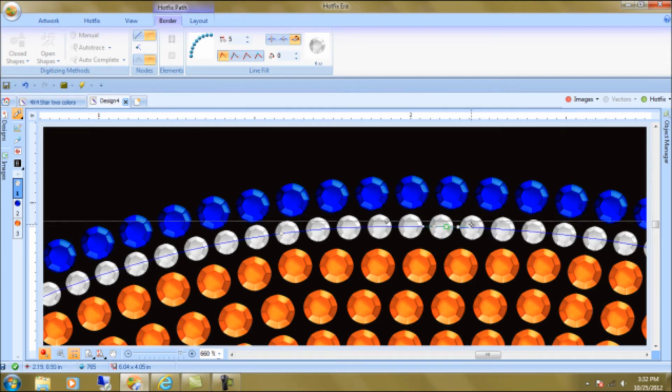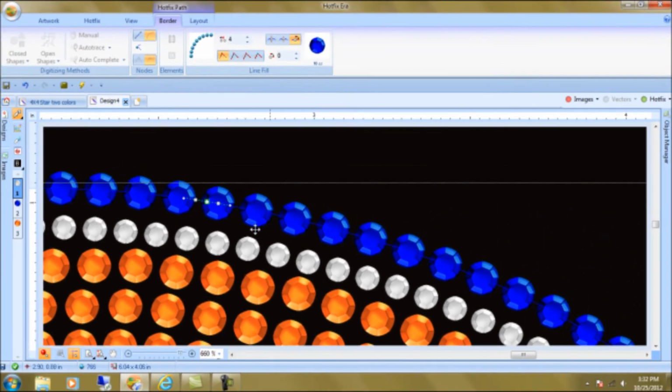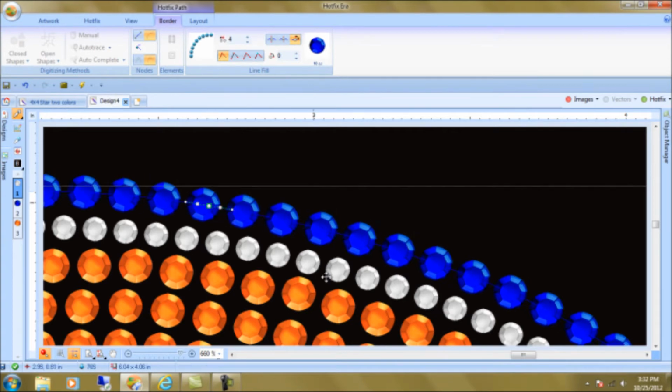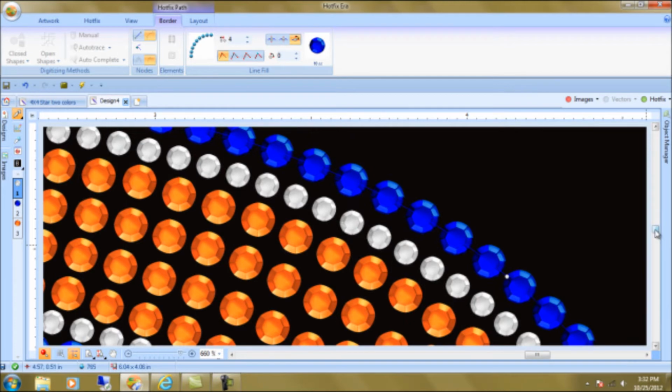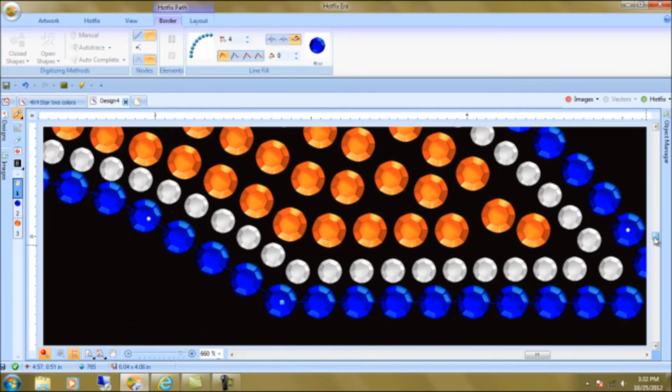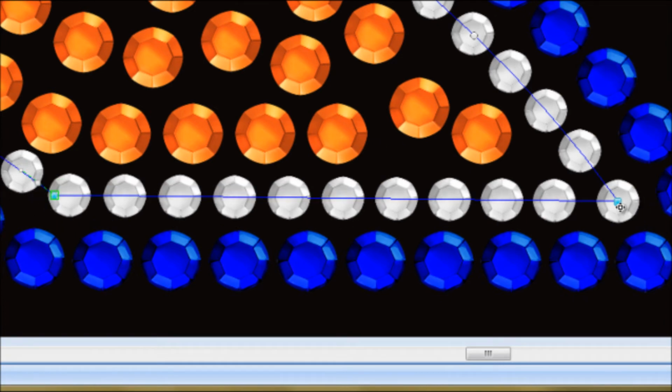And on each end of that node, you have what's called a Bezier grip, which changes the shape of that curve. Okay, it changes the shape from this node to that node, or from this node to the next node down. Okay, and we're getting there, so we're going to move this up, and that's too far, so I'll move that down. A little motion when you're zoomed in this far can be a lot. And this looks pretty good all around here. I may want to taper the distance here a little bit, so we'll do that. And this looks absolutely excellent there.